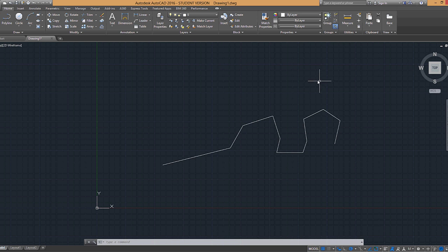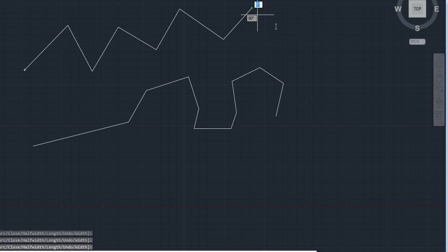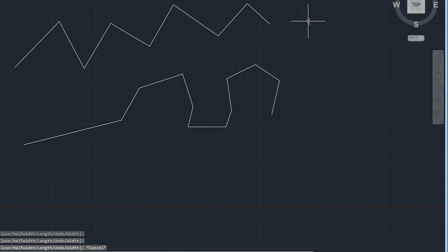We'll now repeat practicing this with the tools polyline, rectangle, and circle, placing random shapes within the model space. Polylines consist of individual segments, lines, and arcs that act as a single object. That's how it differs from the line. And all information in AutoCAD, as I mentioned in an earlier video, is referred to as an object, no matter if it's a line or a shape. So if we go to our polyline, okay, we can either click on the button here, we can type in P-line or PL, okay, is the alias for it. And again, it works the same way as the line until we hit escape and exit it.